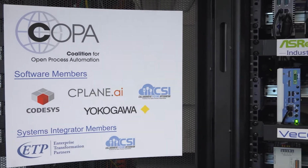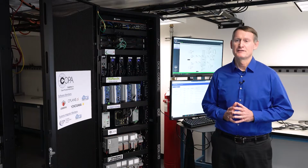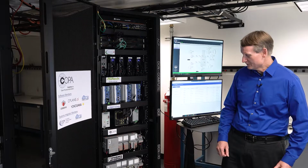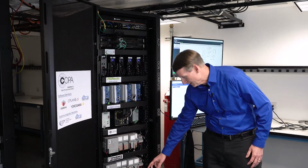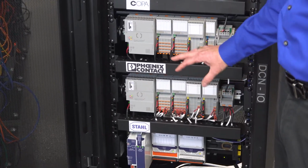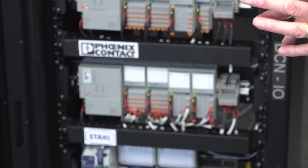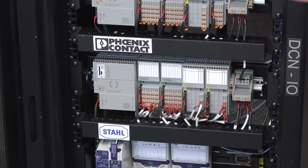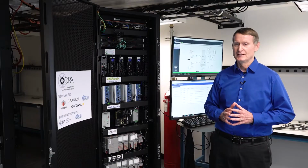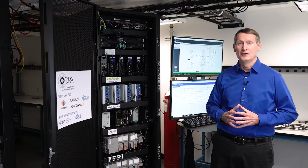All right, the first thing I need to tell you is that the COPA QuickStart system follows the OPAS architecture developed by the Open Process Automation Forum. We'll start down at the bottom with some distributed control node I/O modules from Stahl and from Phoenix Contact. Now, the most important thing to talk about here is the fact that we've separated I/O from compute. You don't have to have compute and I/O modules from the same vendor. That's really important when you're ready to upgrade your compute capability because you won't have to lift field wiring or replace any of the I/O.